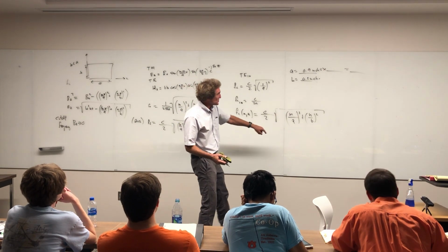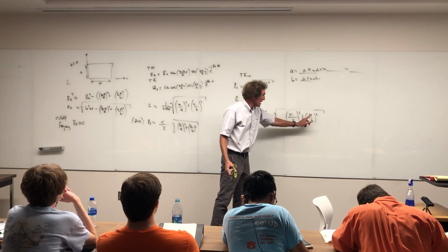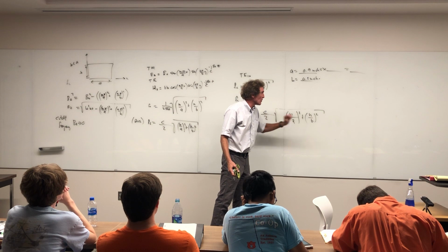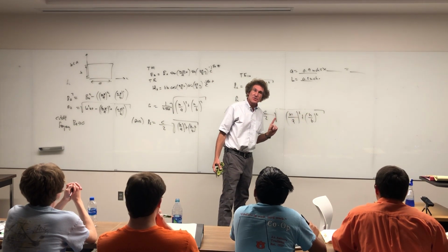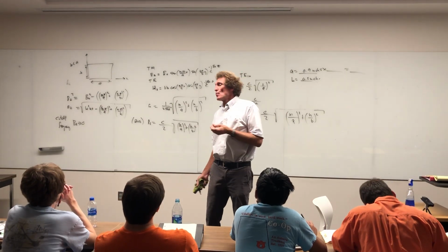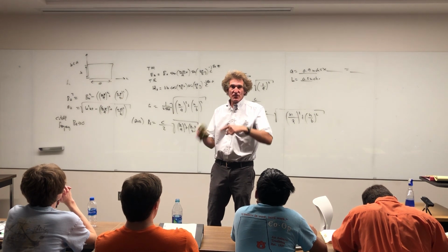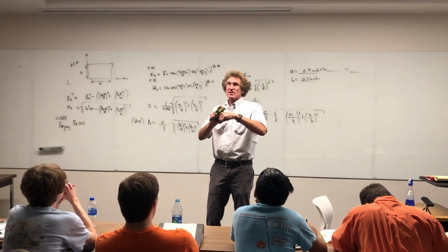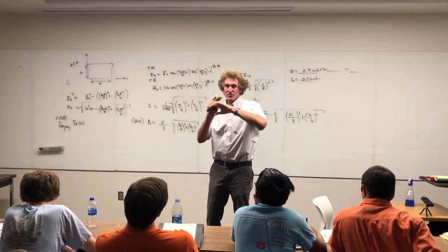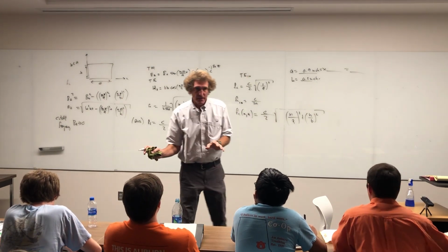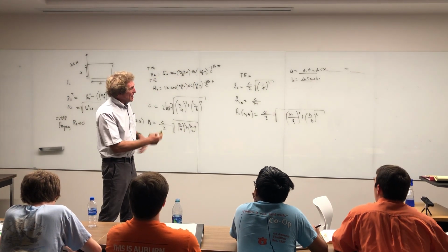Because when this becomes 3, when you have 3 in the A value, and you have 3-0, it'll be the exact same frequency as 0-1, because B is 1/3 the value of A. You follow me in this class? And that's called a double mode, where 2 different ways energy sets up, or the electric field pattern maps in 2 different ways, and superimposes and propagates. You don't have to worry about that. Those kinds of modes, you just use one frequency there. Anyway, if you do that, you'll get it.